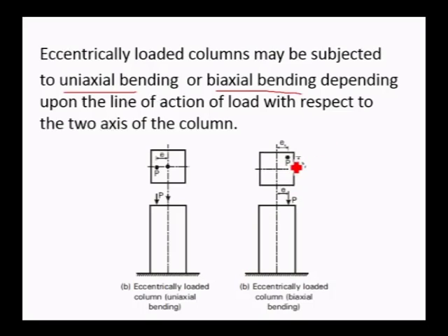If the load is acting at a distance of Ex from the centroidal Yy axis, and at a distance of Ey from the Xx axis, then P is not coinciding with the horizontal as well as the vertical axis, Xx and Yy axis.